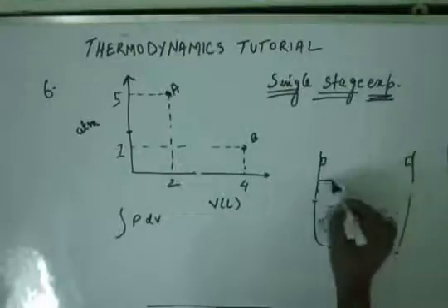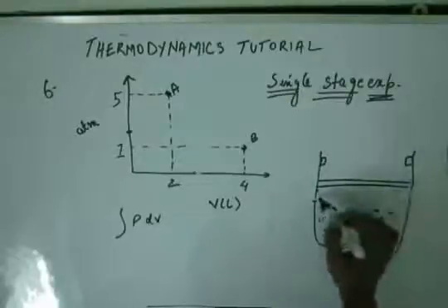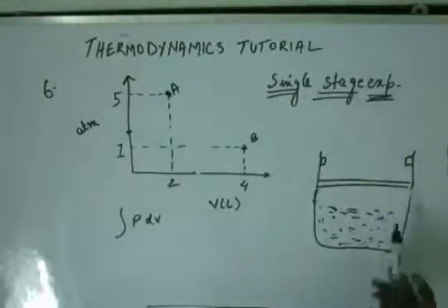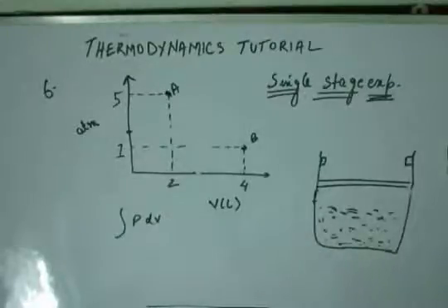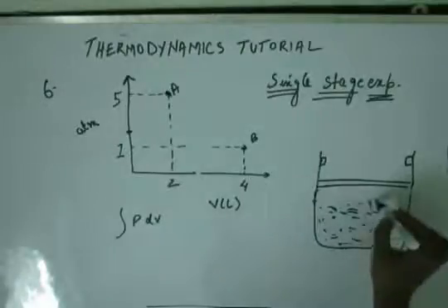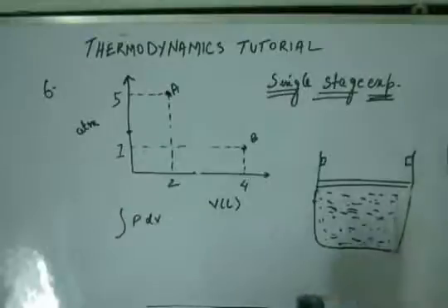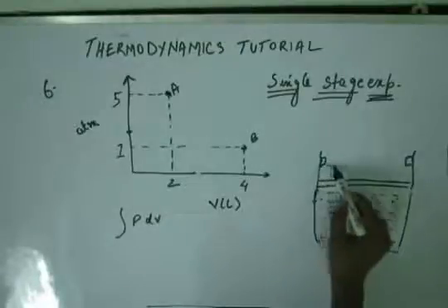Because from inside, what will happen is, suppose this piston moves up a little, the gas will be unaware of this fact. So there will be a kind of vacuum in this region, and then when these gases see the piston is moving up, they will come up to fill this vacuum. So actually from the lower side, the piston will not be having any pressure. From the top, it will be having some. So it will be running up, and the resistance that it will be having is the external pressure. So the pressure on the piston technically will be constant throughout the process, and that will be the final pressure that it is going to have at this point.